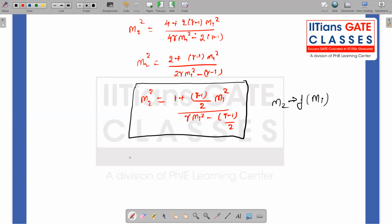Similarly here, you see, if m1 is greater than 1, then m2 is subsonic. This is important. So for m1 that is supersonic, m2 will be subsonic. So the flow will be subsonic behind the normal shock wave. And for m1 equal to 1, I will get m2 also equal to 1. That is fine. That is a weak solution, the weak normal shock wave. That means the Mach number stays the same.